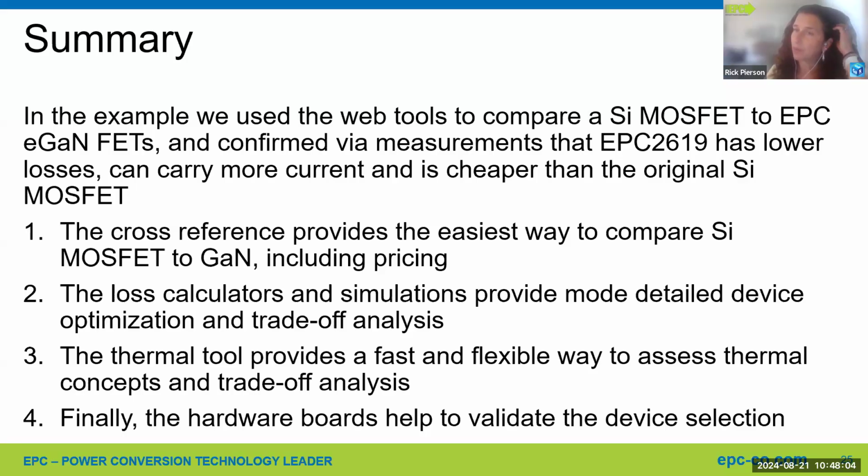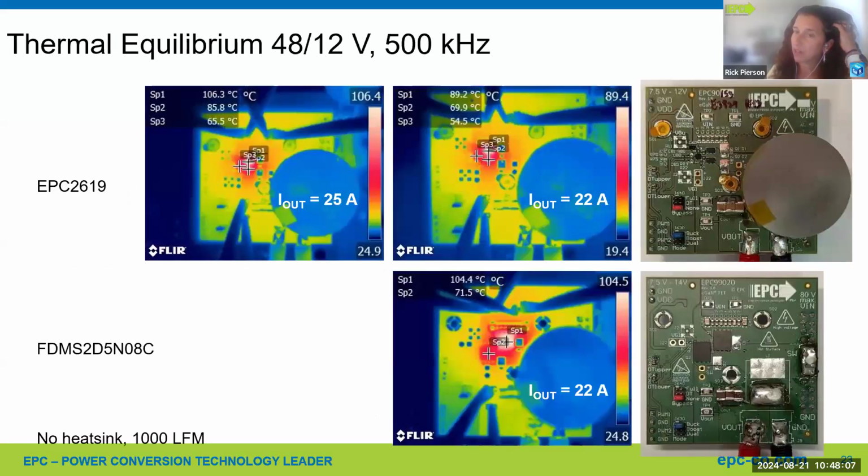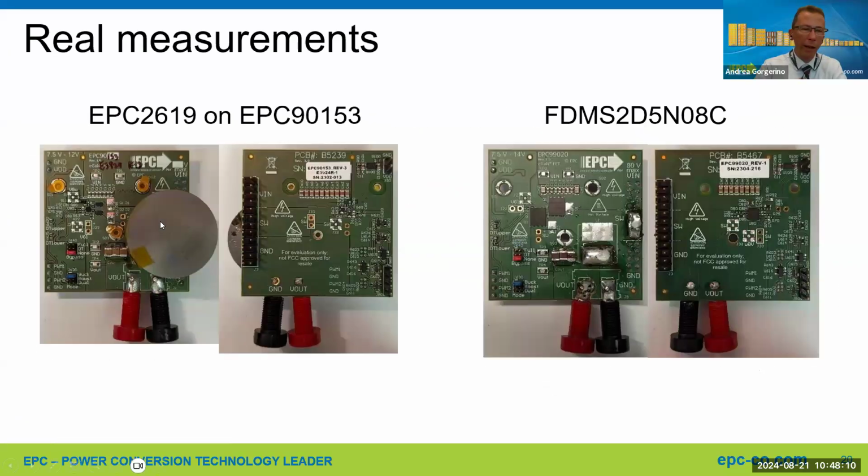On slide 20, can you go back and show where the GaN FETs and the silicon MOSFETs are on each PCB? Oh yeah, you can. I should have highlighted in red. You can see this is actually the driver right here, and the 2 high side and low side. You can see my mouse, right? Here are the decoupling caps that I was mentioning before. So that's the power loop right here. The 2 GaN FETs are there, and then on this side, everything is much larger. You still have the decoupling caps over here, but the 2 FETs are very large. And the gate driver had to go on the back of the board itself, right here.